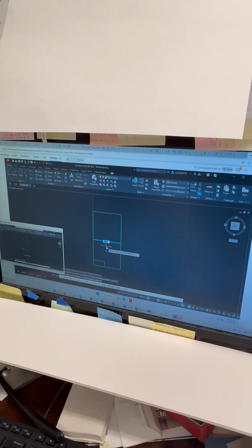All right, now continuing on with this, you're going to select the resulting line you just created, and this is going to be the width of the walk-in closet, which the dimension is 7'9.5". So I'm going to type in 7'9.5", and hit enter. Finally, I'm going to pick this resulting line, and I'm going to move my mouse, and look at that, 3.5 inches. All I need to do is pick.